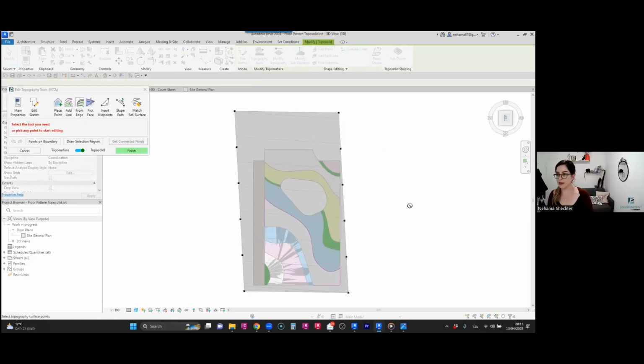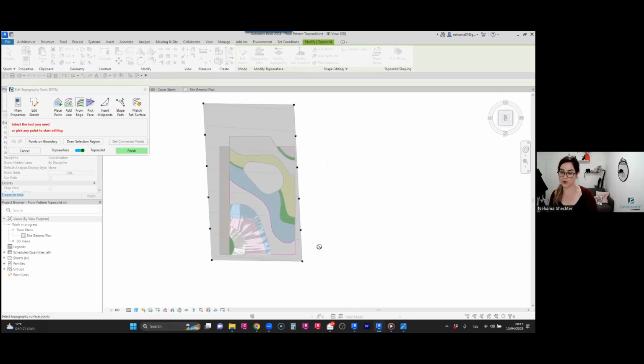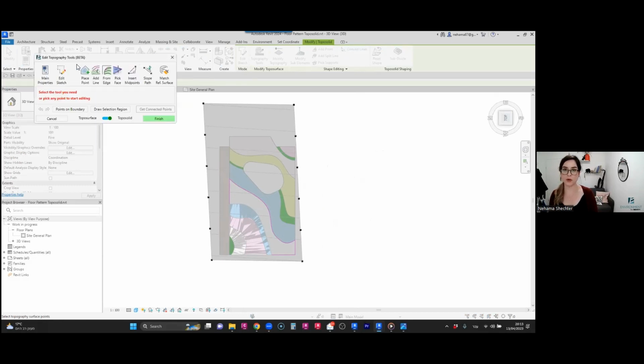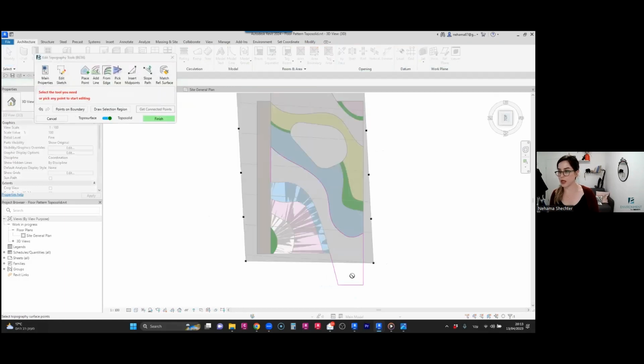So we actually added the option to extrapolate the surfaces. Basically, our algorithm can make an educated guess as to what your slope is supposed to look like. For example, let's edit this sketch and take it just outside of the boundary, just like that. You can see that my boundary is outside of the reference surface, and there's no information as to what the elevation is supposed to be there, right?